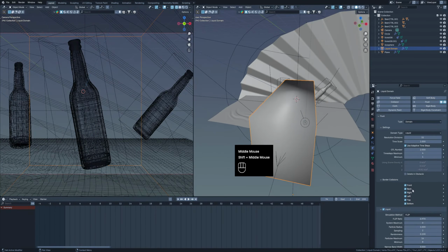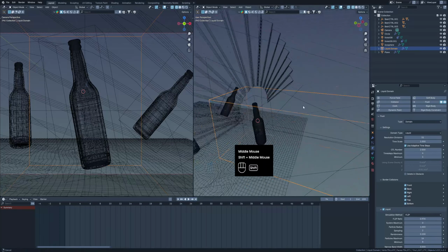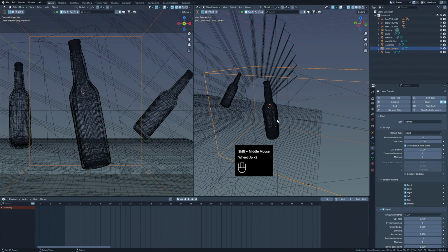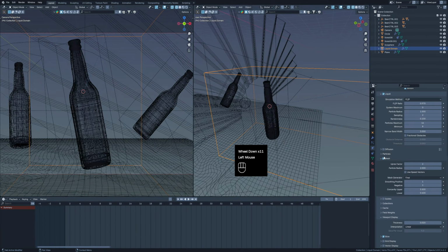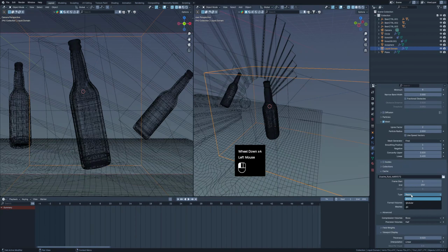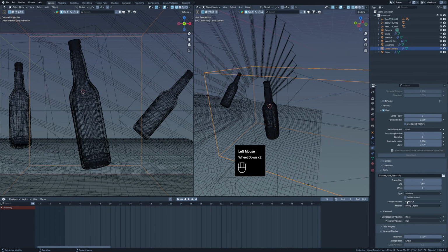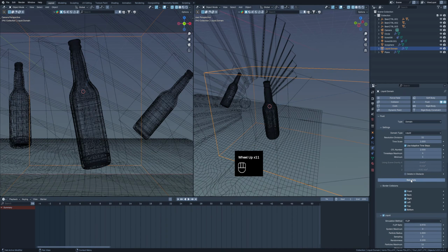Alright, so right now our fluid simulation is pretty simple, but you need to know that Blender likes everything to be baked. And right now we are going to work on this, so let's scroll down to the Cache tab. And here you need to change the type to modular and check is resumable. And now we have more opportunities while working with the liquid simulation. And if I scroll up right now, you can see we have 2 additional buttons.